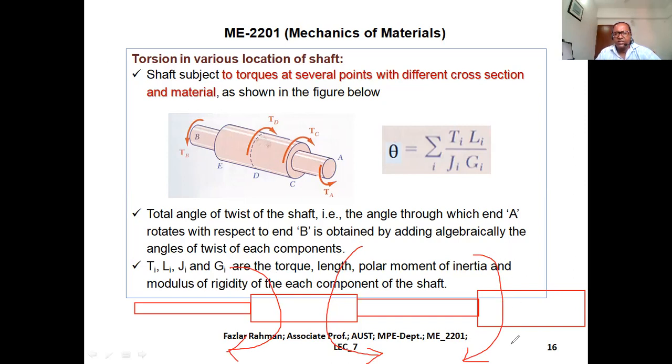So you see these two torques, this one and this one, clockwise. So I'm saying this is 500 and this is 300. So 500 and 300 rotating clockwise. So obviously this one will be how much? The summation of all torque has to be 0 because this is a solid body and we're working with a static body. So this one will be 800, right? 800 Newton meter or 800 foot-pound, depending on the unit, right?